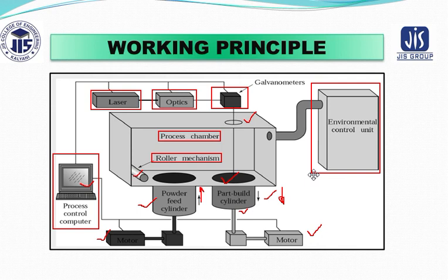So when you are performing the sintering operation, you have to keep in mind which material is most effective. My suggestion for that is polymer, because it is smaller, less expensive, less complicated, and the laser required for sintering is simpler. Now with ceramic and metal, it is common to sinter only a polymer binder which has been blended with the ceramic or metal powder, and then to complete the sintering in a furnace.